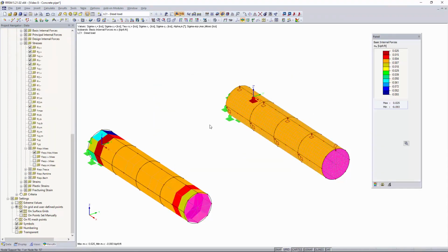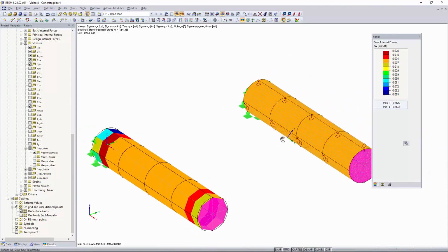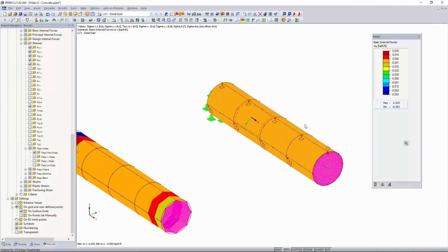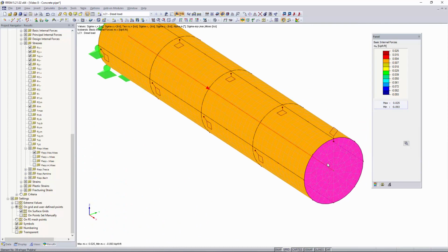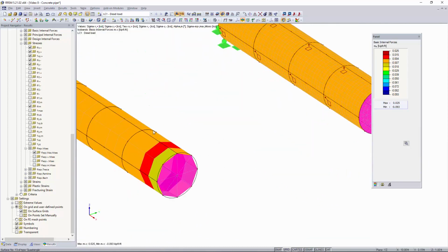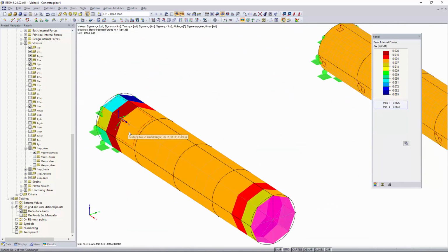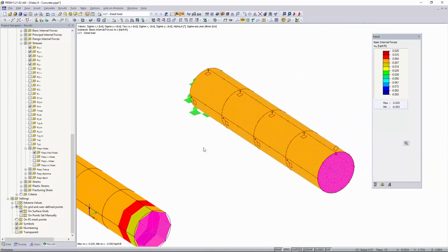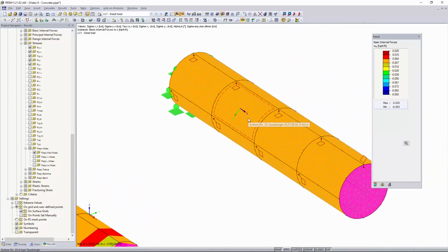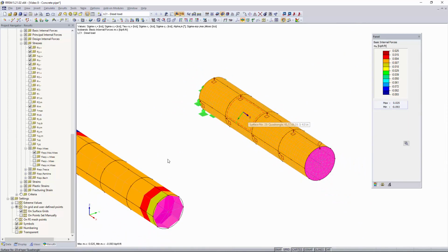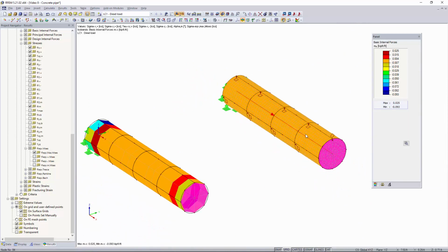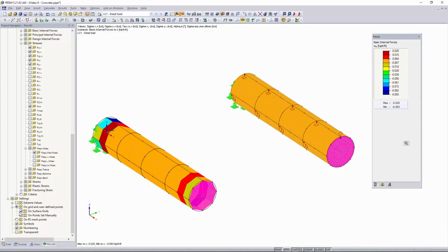Our results are generated, and now you can see how much finer and how much better our model with our smaller FE mesh looks. As you can see, we had a 1 foot FE mesh over on this model, and on this model we have a 0.2 foot FE mesh length. And that gives us a more accurate representation of our model with a finer FE mesh compared to the more blocky FE mesh over on this side. So now let's view the results.